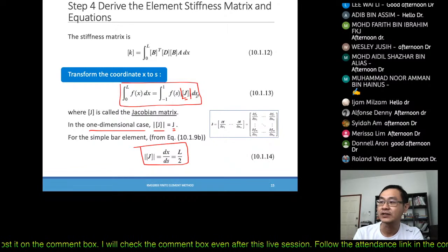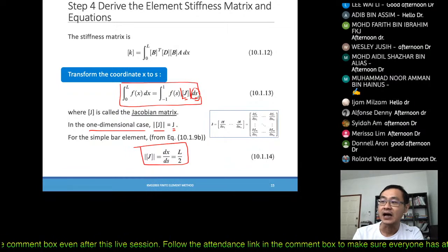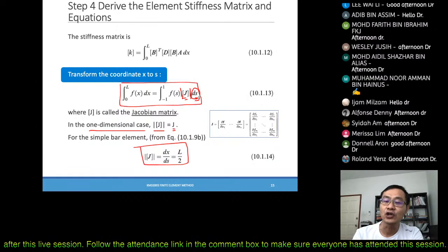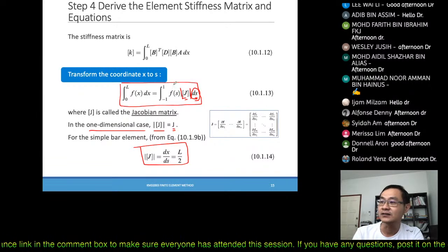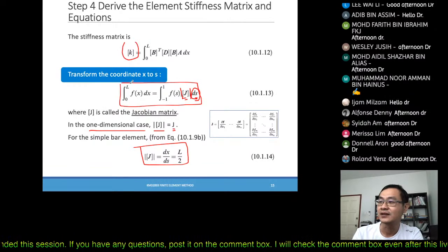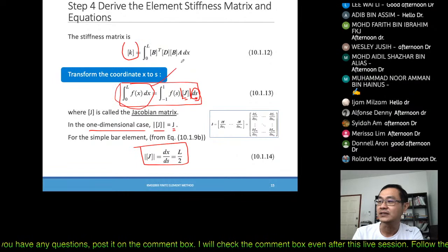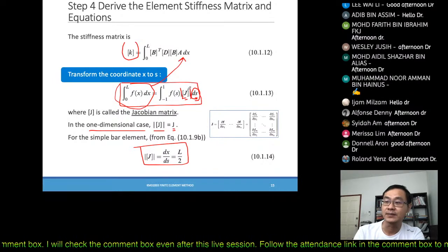So remember, we have this S domain, right? Our coordinate, or the node itself, is expressed in terms of the natural coordinate. So if we need to obtain the stiffness matrix, therefore this part has to be inserted here, right? That's why we have to include these Jacobians.